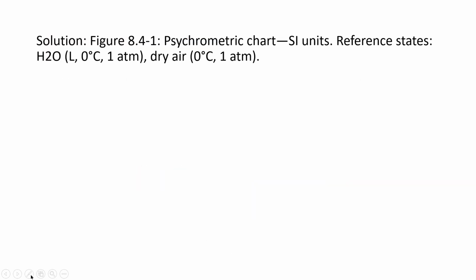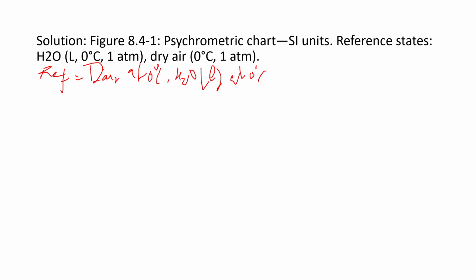So the reference state that we will take is dry air at 0 degree and water at 0 degree. So let's draw the table here. Substance, moles in, enthalpy in, moles out, enthalpy out.